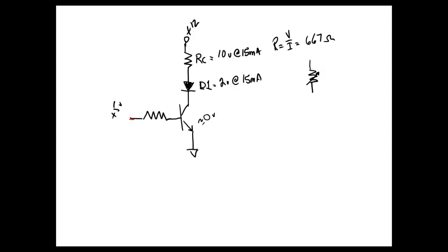So our math is going to be perfect, right? But our components are not. So we understand it's not going to be exactly what I designed. We'd look at our LED and ask, what would the LED handle? Well, it could probably go up to 20 milliamps, and it could probably go down to 10, and it would still light up. So all we're going to do is round that resistor to the closest standard value. Sometimes we might round up, sometimes we might round down.